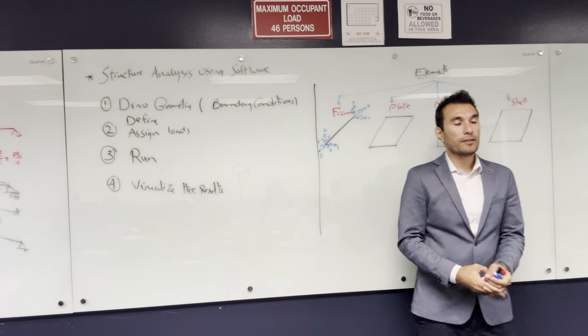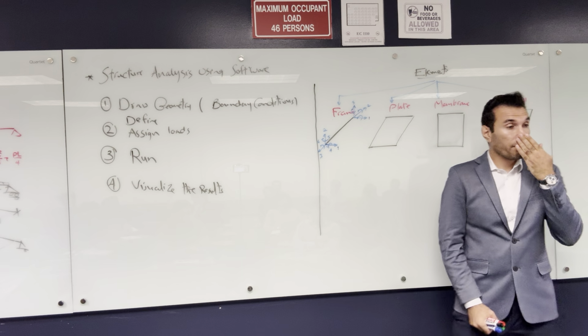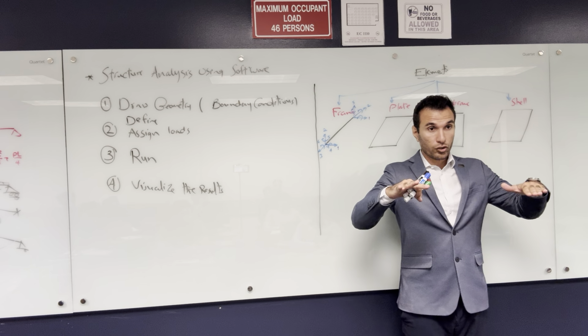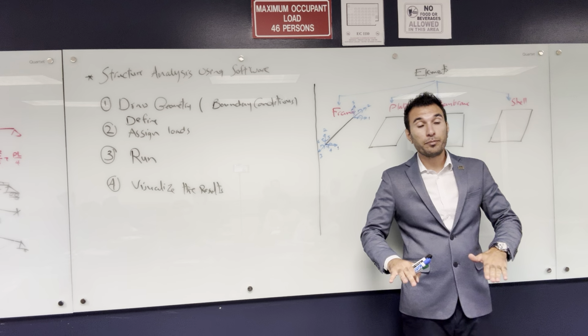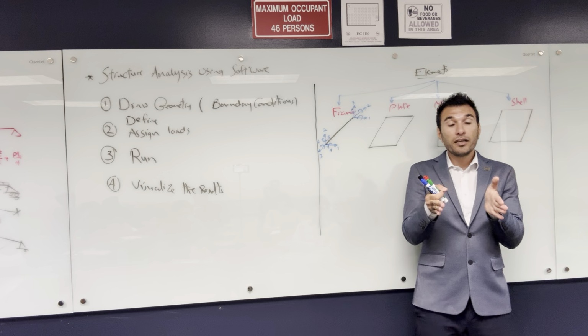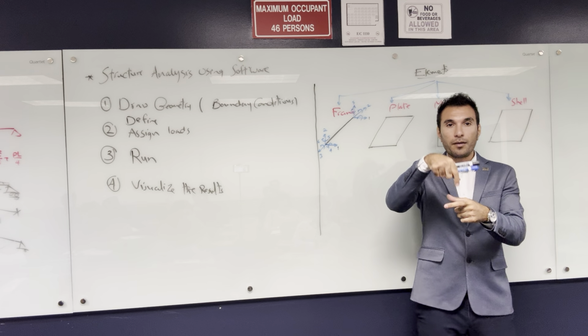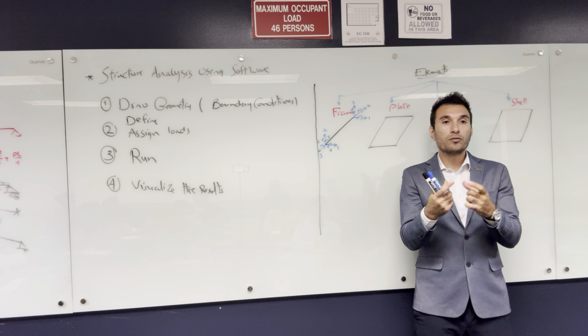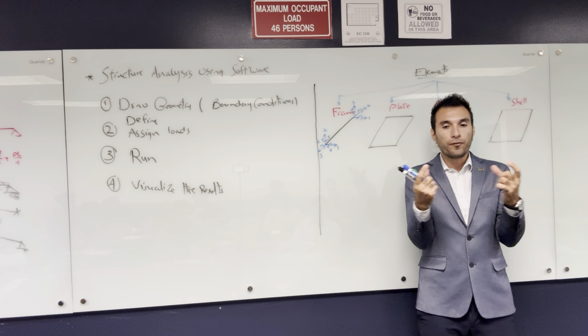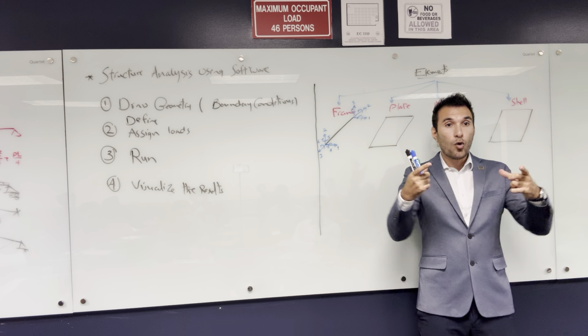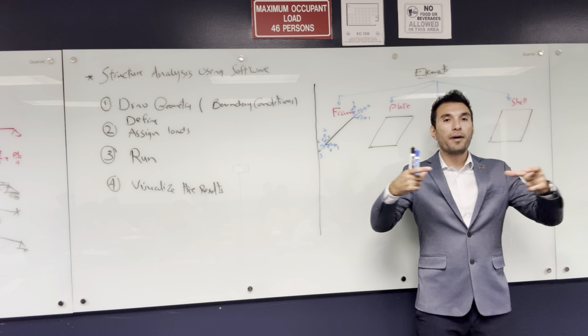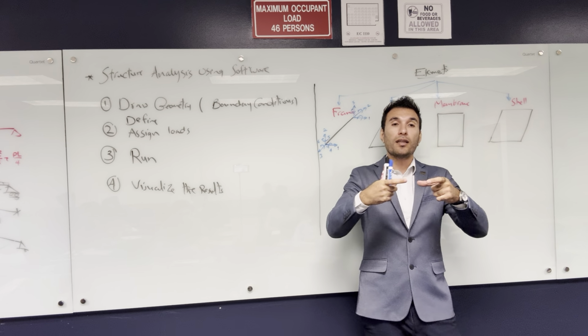Okay, let's talk 5 minutes about foundation. When we have a structure, we need to have foundation. The foundation can be different types. It can be isolated footing, you can make a square and the column is coming onto the square. And sometimes when two footings are very close to each other, we combine, it's called combined footing. You combine 2 columns together.